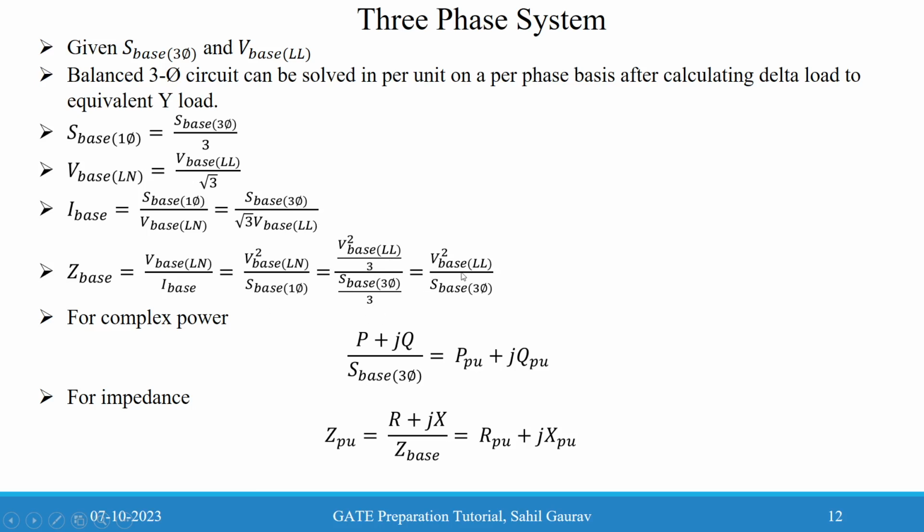So you will get V base LL square divided by S base 3 phase. In the problem we are given this S base 3 phase and V base LL, so just keep this in mind.